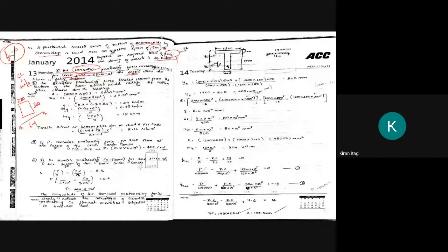And the second case is that the eccentric prestressing force is located at how much? 100 mm. Eccentric he has given, that is located 100 mm from the bottom of the beam. Bottom of the beam means from here to here he has given 100 mm, which means that eccentricity will be equal to 50 mm, because this is 150, from here to here we need, that is E, at the bottom of the beam, which would nullify the bottom stress due to the loading.